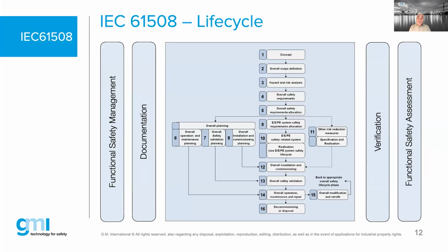And that's where the misunderstanding in the industry comes from, that people think we are buying a SIL 3 or a SIL 2 certified device. No, you are buying a device which is suitable to be used in a SIL X, and the certificate, which is the result of the assessment, will reflect what the findings were for that specific instrument or device.